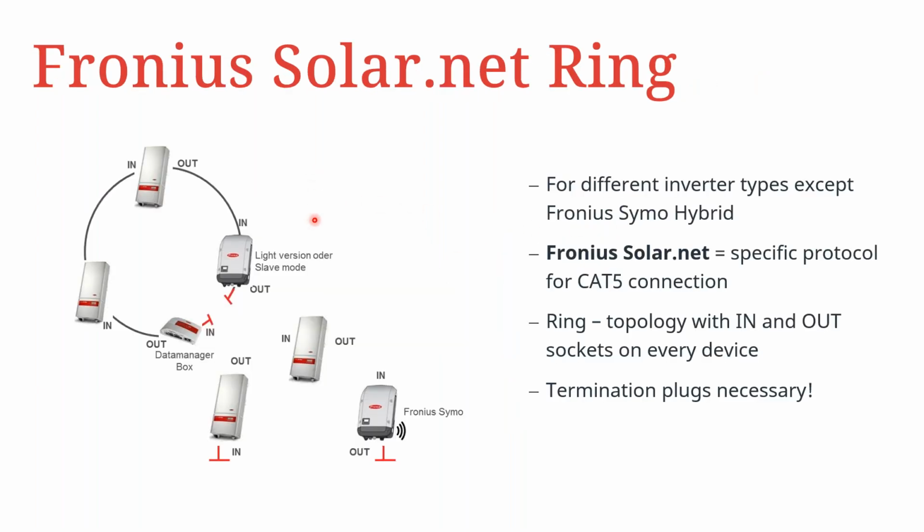So as mentioned before, there are two possibilities or variations for using the SolarNet ring, and there are applicable components. In this example, we are seeing two variations. In the first, we have the data manager box, operating outside of the inverters, or another variation where we have the data manager operating within one of the inverters, so it is integrated in this case as a card. So in the first example here, we have a data manager box, but in the second example, we have it integrated as a card version in an inverter.